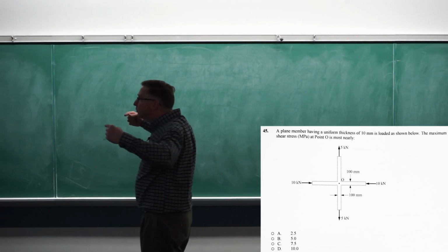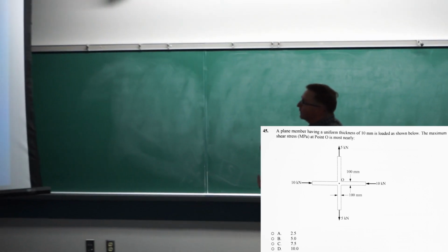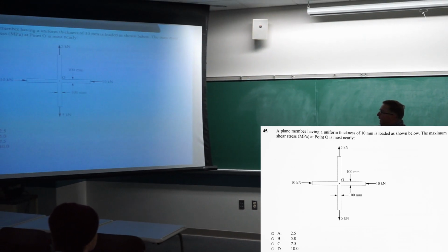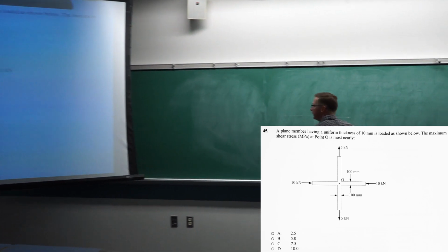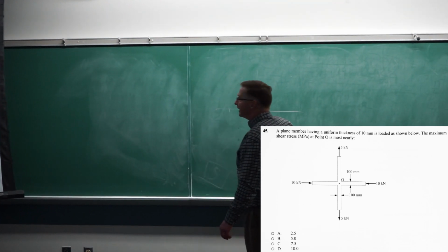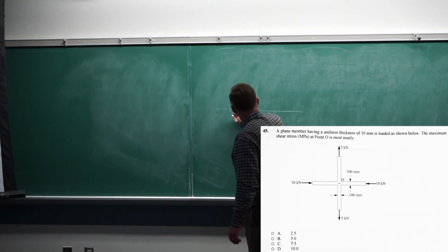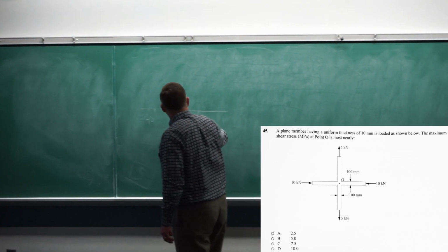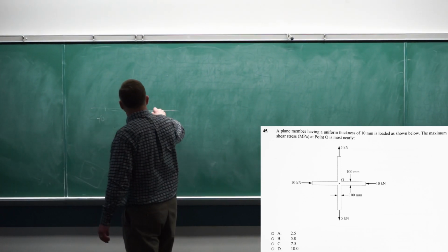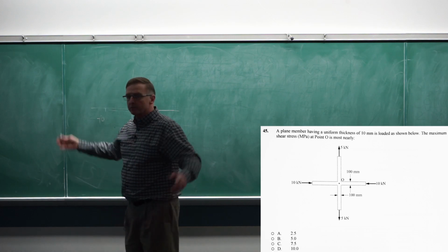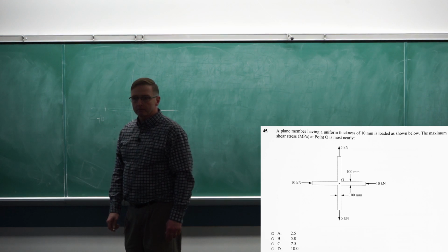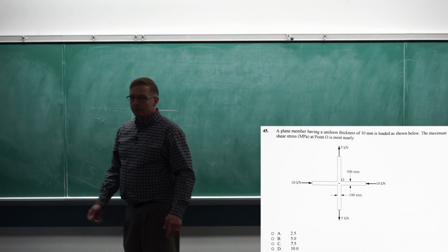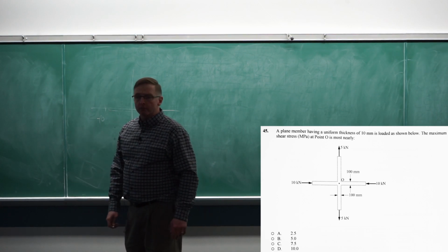In the middle you're going to have a compression of 10 and a tension of 5, and the areas are consistent left to right and up and down. That sets up Mohr's circle with minus 10 and a positive 5. Its diameter is 15, its radius is 7.5. That's your maximum shear stress. Even without doing the area calculations, I could see it was 7.5 that quickly.